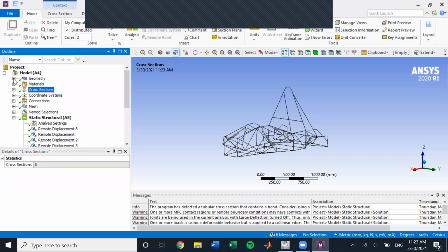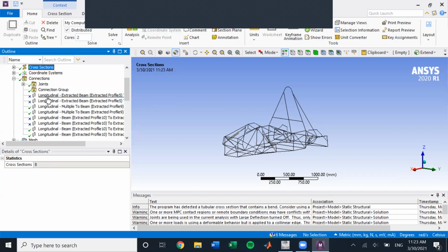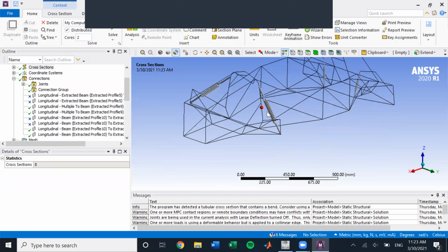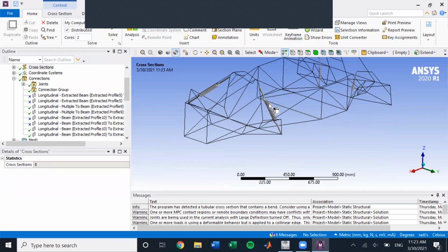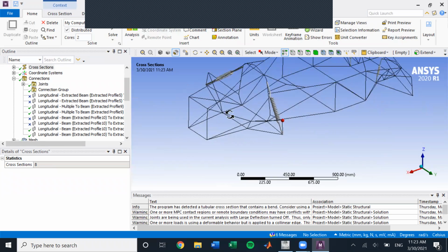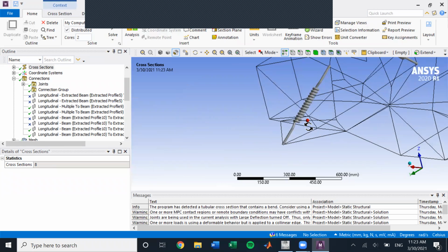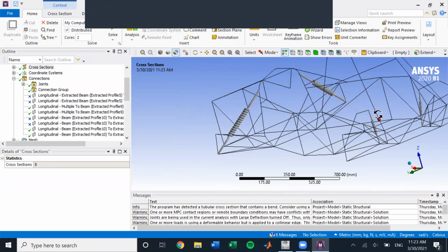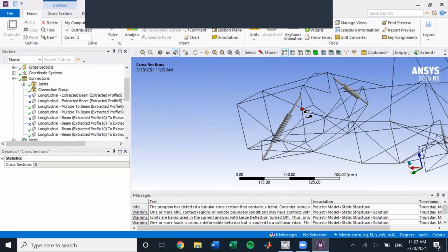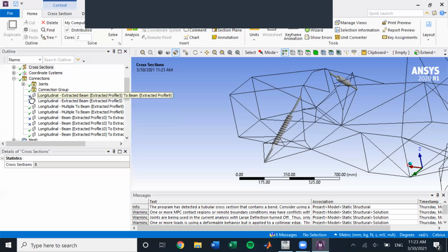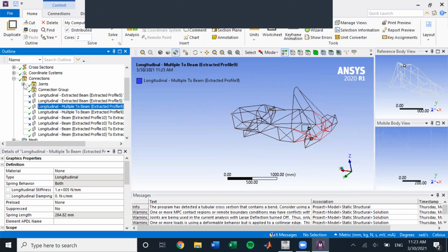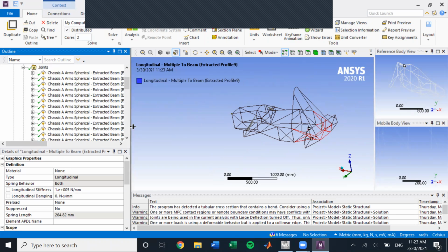And if we go into connections, you'll see a lot of springs here. That's because I was just playing around with it with different locations and also with or without the push rod and rocker in the front. Because if we had the push rod and rocker in the front, then the spring would go at the end of the rocker to the chassis, similar to what it's like in the rear, rather than being direct acting in this way. So yeah, the X's just means I've suppressed some of them, and I'm just keeping the ones that are visible. And the joints we'll see are exactly the same.